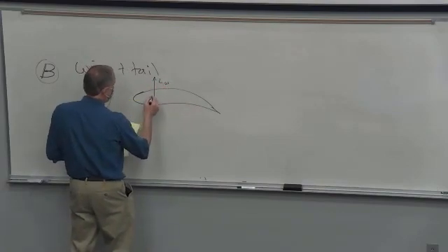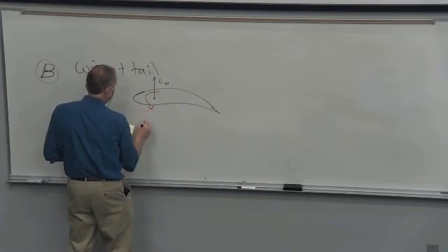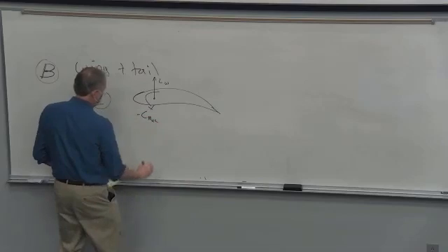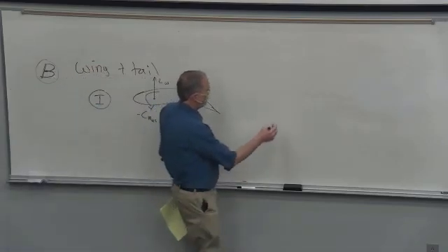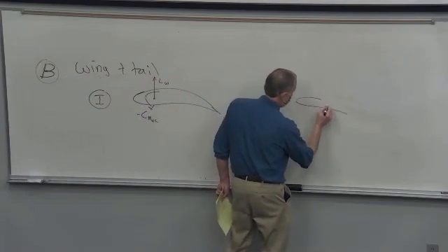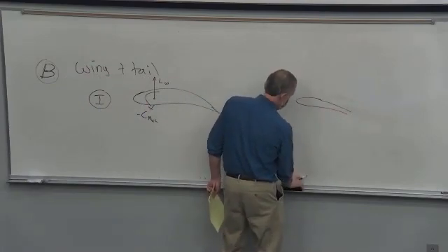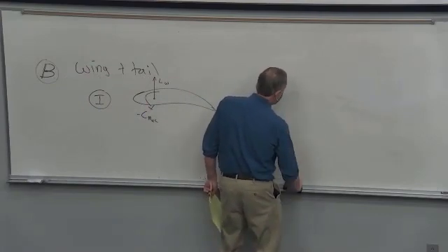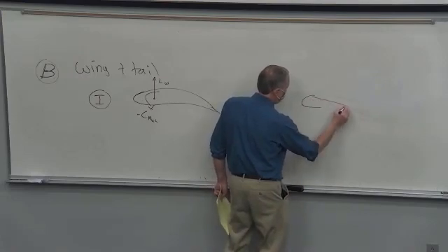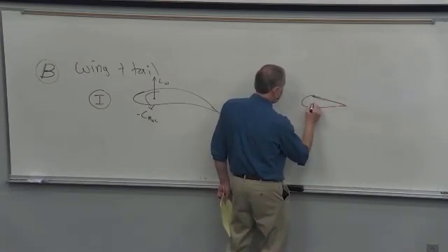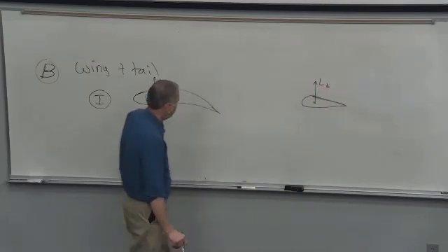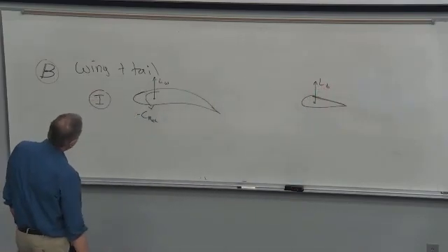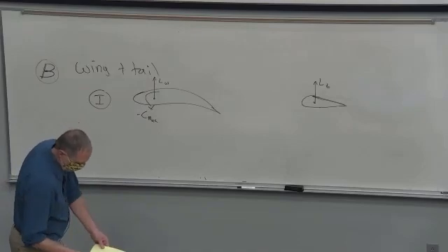And notice I've done a positive cantilevered airfoil because they're aerodynamically efficient. We get a negative pitching moment from that. And then we're going to stick a tail back here. And we'll make the tail symmetrical so that we don't get any pitching moment. So there's a symmetrical tail. So we just get lift of the tail. And then we have to say, well, where do we put the CG?